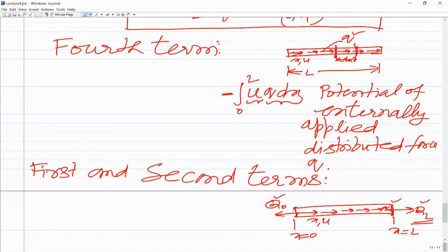If you look at the left side you have this Q naught, and the outward normal to this left section is along the negative x direction. So the positive axial force would be along the negative x direction. So the axial force is positive on a negative face along the negative coordinate direction. So what I have shown here, Q naught and QL, are the positive axial forces.